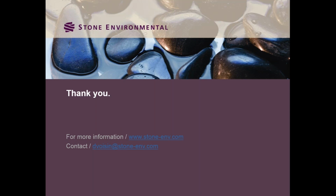I think one thing that we didn't mention is that it's not just for surface sampling, right? You can say a tiny bit about that. Sorry, I glanced over that. So we've done ISM even in vertical. We've established a grid of 30 squares, and collected the replicates using Macrocores down to 5 feet. So then taking the 0 to 5 interval and taking an individual increment from there, and another one, and having all of the 0 to 5 represented as the increments.